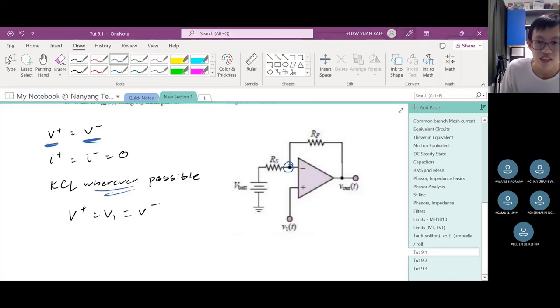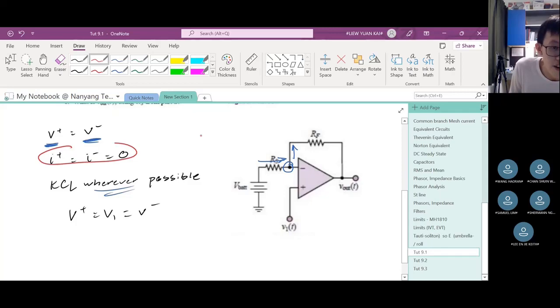So you focus on this node. You can really assume that it goes in this direction and this direction. Or you can also assume it goes to this direction and this direction. Or you could also assume it goes to this direction or this direction. I'm telling you, it really is just any way. Just as long as you keep consistent with following KCL, current going in is equal to current going out, any way you assume should be no problem. So for the sake of simplicity, let's just assume this way. Move in like this and move like that. Let's make it simpler. Like this, like that. Okay?